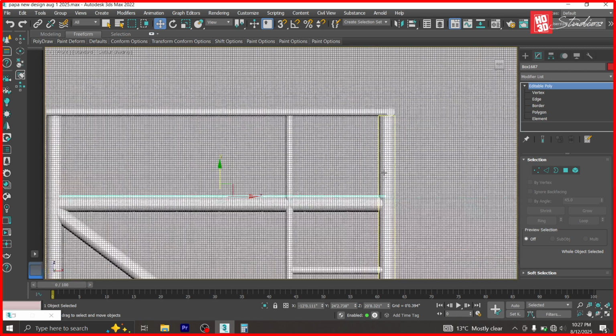Now, another thing I've not considered, which is part of a building code, when you're making balustrades, it's often recommended that your balustrade should not be less than 3 feet tall, but 3.5 feet, which is 42 inches, is often recommended.